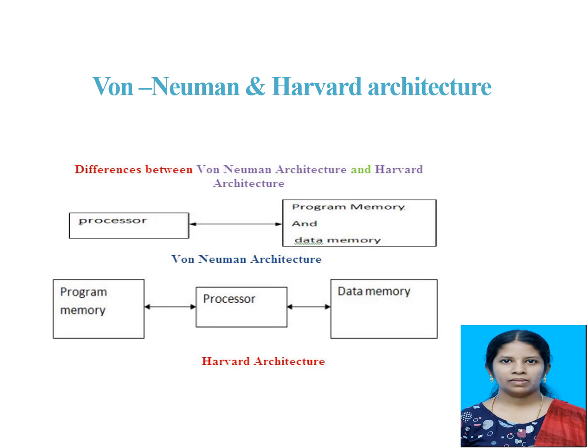Harvard architecture has many features: separate memory spaces, fixed instruction length, parallel instruction and data access, more efficient memory usage, and it is widely used in embedded systems. The advantages of Harvard architecture are faster processing, improved security, and efficient use of resources. The disadvantages of Harvard architecture are complexity, higher cost, and less flexibility.